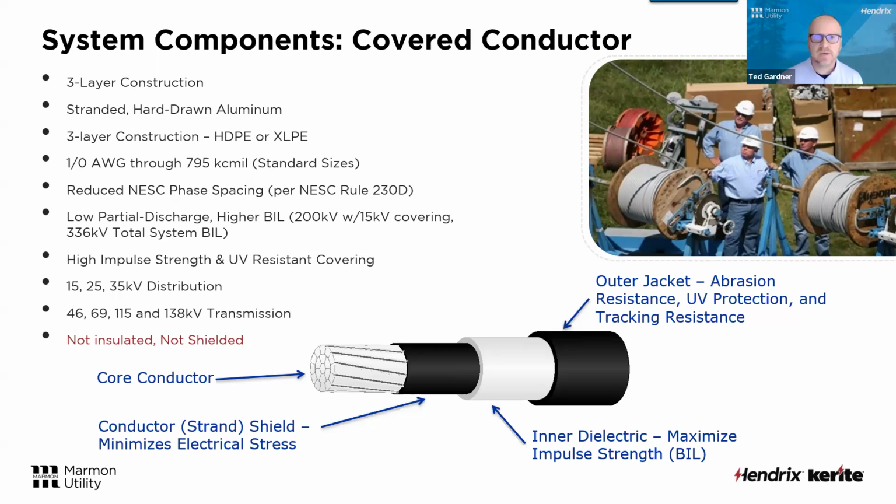And like I said, that's the same polyethylene material that we make all of our insulators and all of our spacers out of. So we know that all those materials are going to behave the same from an electrical perspective. I'll refer to it a lot as a spacer cable system, and we look at spacer cable as an engineered system. All these component parts work together from a mechanical and electrical perspective. We've always maintained we want to manufacture the full system, that way we know that everything is going to work and we get the most reliability out of it.